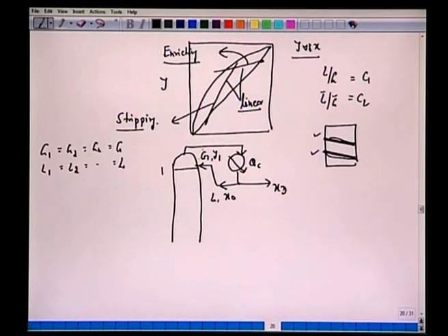We have y1 and x1, but still this is L and G. At plate 2 we have y2 and x2, but we just have L and G. All L's are the same and all G's are the same here, and it's a total condenser, so we have y1 equal to X0 equal to XD. The molar flow rate is D here.